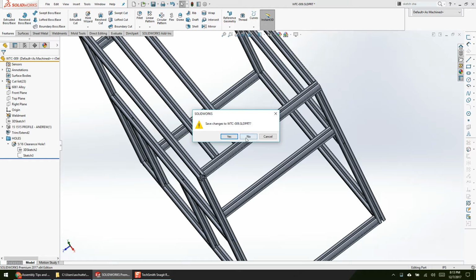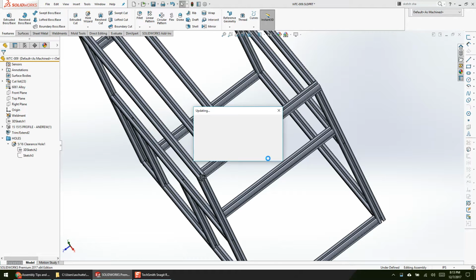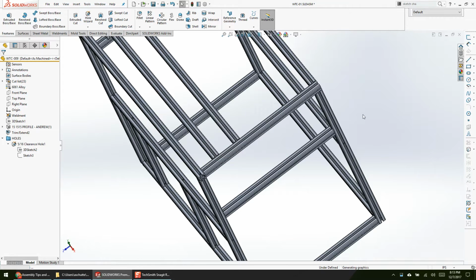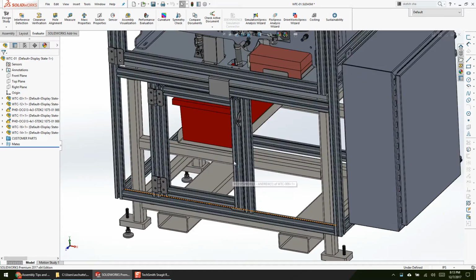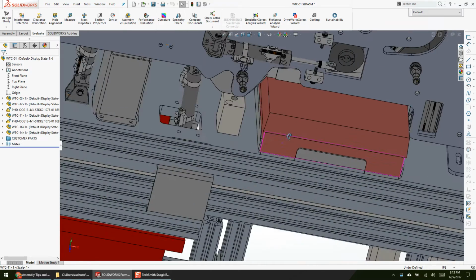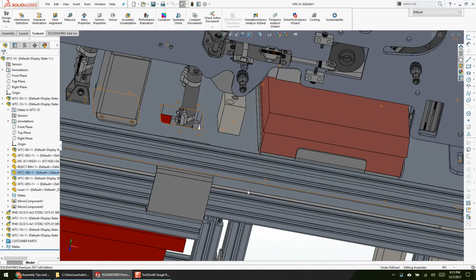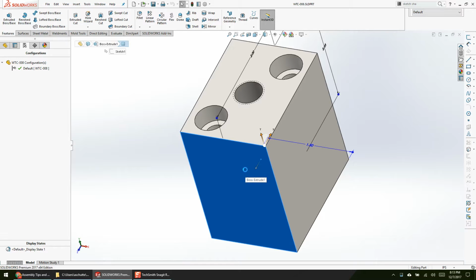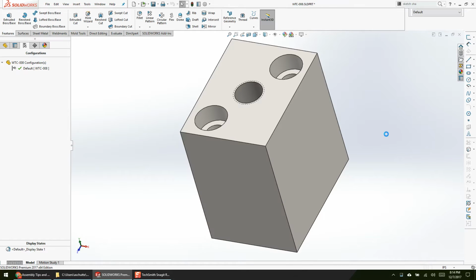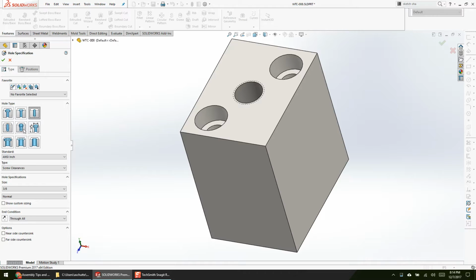So have you used hole wizard before? I just regular 2D surface. Yeah. Okay. That's basically giving you that first pick that you did on a surface. With your regular hole wizard, when you're on a surface, it gives you that surface to start on. It gives it a couple dimensions. Here, I'll sketch it. You don't have a face to start. So I'll make it more simple here.